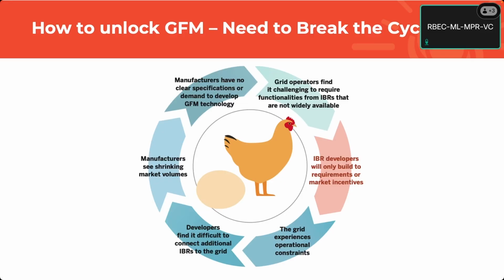In some cases, there's no difference, we're told. There are manufacturers who have said they're not able to do a DC coupled hybrid plant that's grid forming. So if you have an energy supply like a PV plant and a battery on the same DC bus, they have problems controlling their DC bus. And so they won't offer that product. You have to have it decoupled with separate inverters. Other manufacturers have apparently solved that and are now able to do DC coupled grid forming. So there are DC side considerations that the manufacturers have to figure out, but it's apparently solvable.